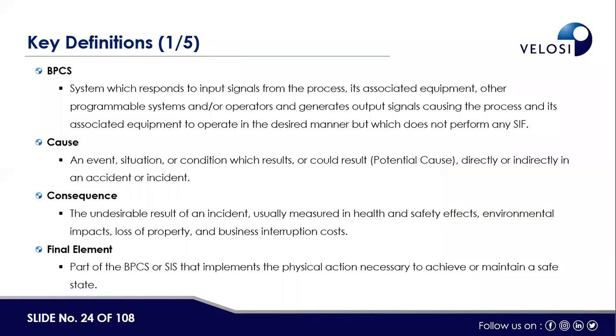Now, from a definition point of view, there is a big terminology we normally use in SIL. I know that in 2 hours we will not be able to train you on the full SIL process, but you would be able to have a fair idea of what SIL is and how SIL assessment is done. That is basically the focus. So BPCS is the basic process control system, which we normally call the instrumentation and control system of the plant.